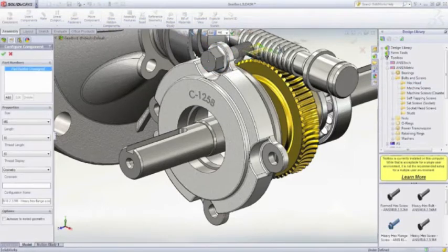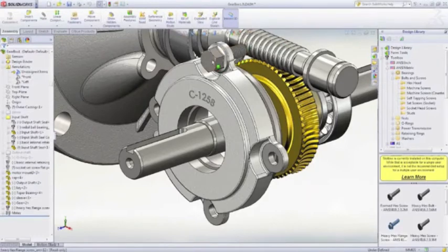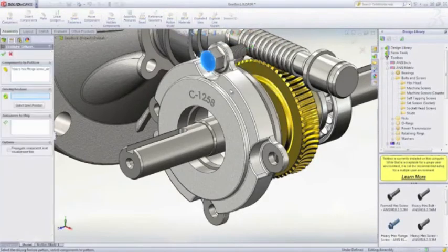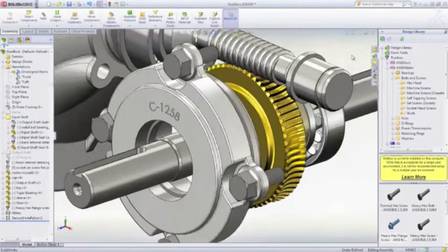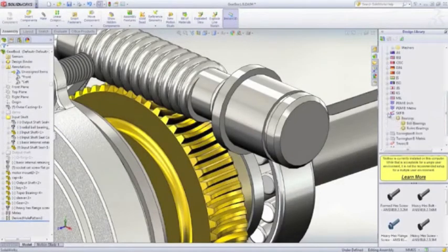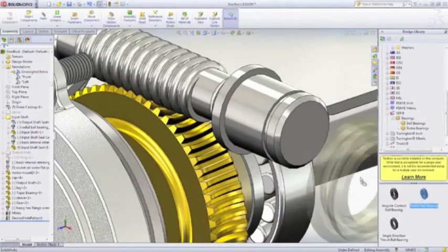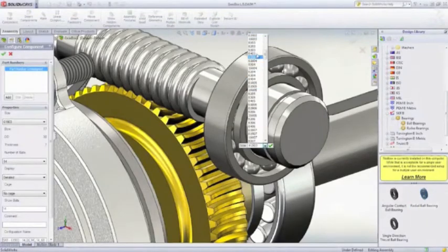This screw is automatically sized to fit the clearance hole where it's dropped, and the length can be adjusted within the available sizes for that screw. Bearings can be applied the same way, auto-sized to fit the shaft, and you can select from various width and OD combinations.